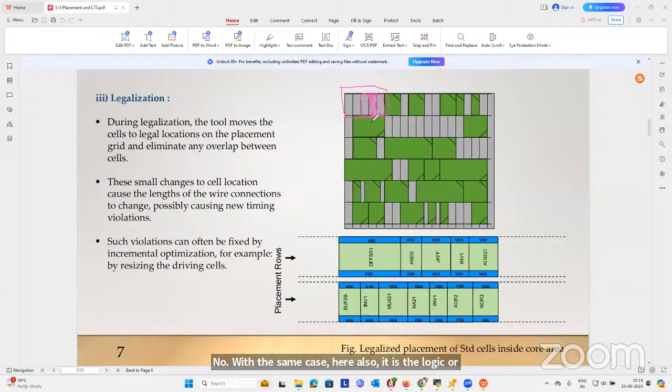Yeah, Bhuvaneshwari, please tell me your question. Can we create one layer for standard cells and another layer for macro cells differently, and interconnect through our layer? No, no, no. All the standard cells, all the macros. So a macro is nothing but a small chip, an IP. If I am doing an SoC, my IP is a wireless chip. I have a Bluetooth and Wi-Fi module in that, which has a 4 metal layer, 6 metal layer design.